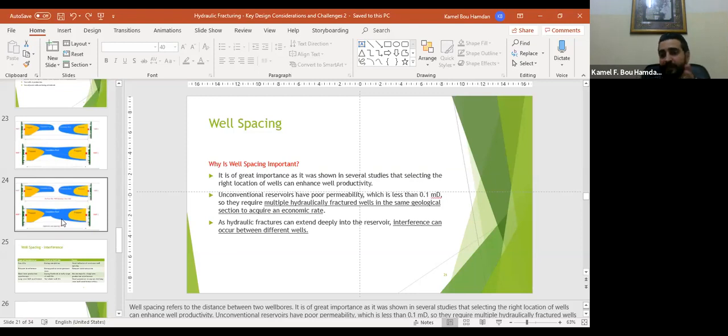We don't want any leakage to occur from our well into the areas where we have the fresh water. The second thing that might occur, however it doesn't really occur that much, is if we have a fault plane. That's an old fault plane which is going to be induced by our fracture. If this happens, then it might create a pathway from our reservoir towards the surface.